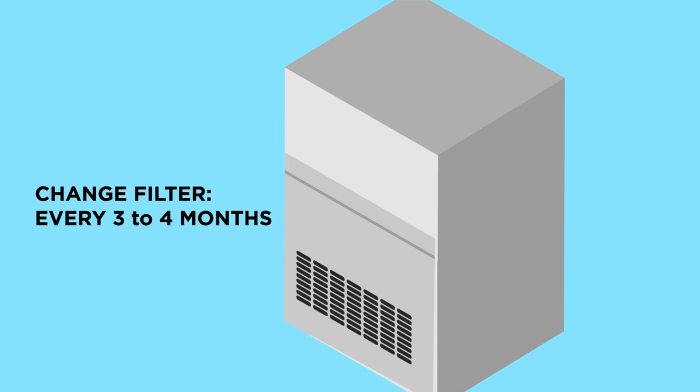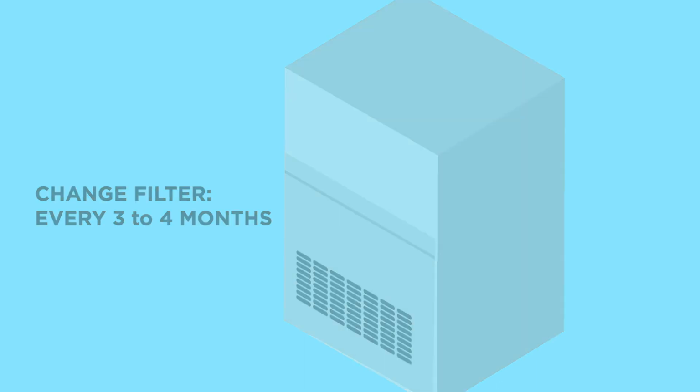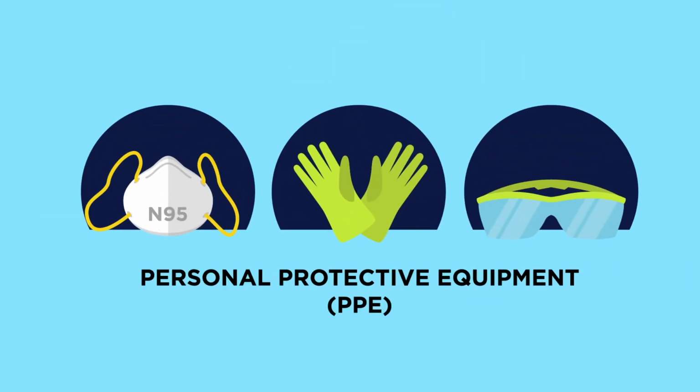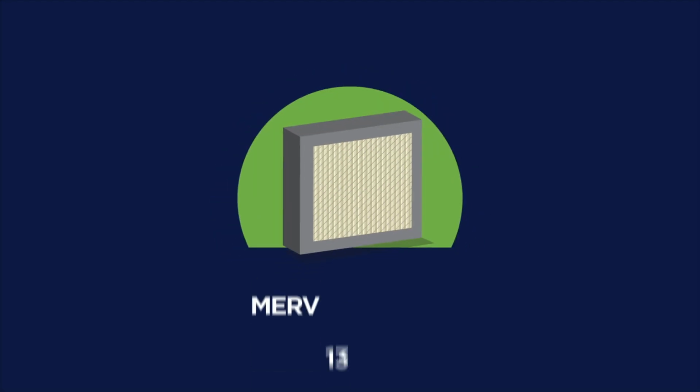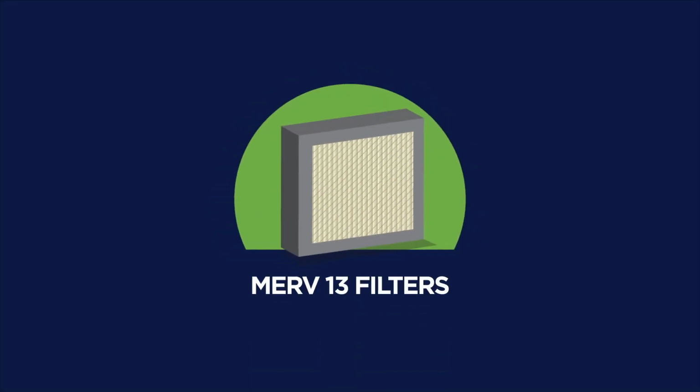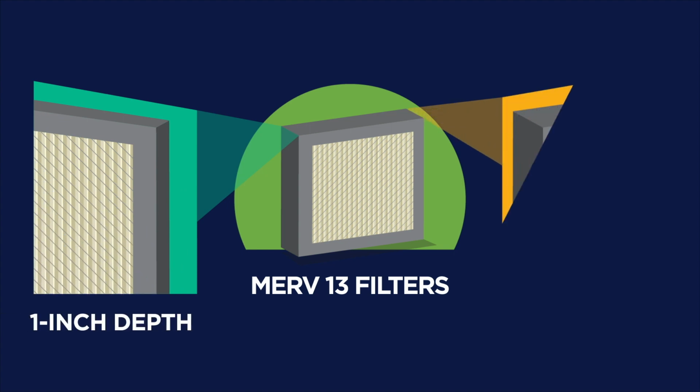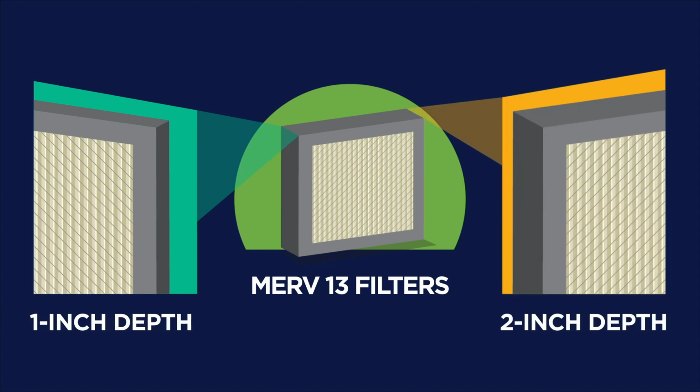Filters should be changed every 3 to 4 months. Technicians should wear appropriate personal protective equipment when changing and disposing of filters to avoid inhaling loose particles. MERV 13 filters are widely available that fit into 1 or 2-inch deep filter slots.